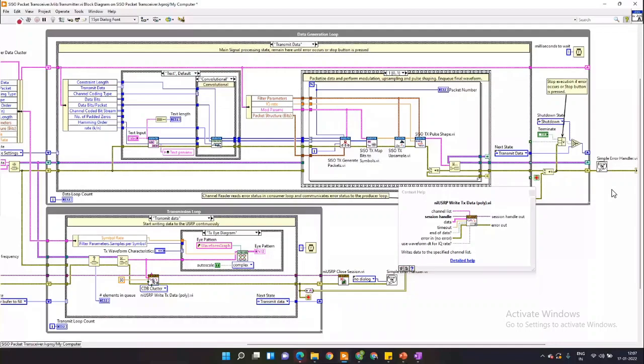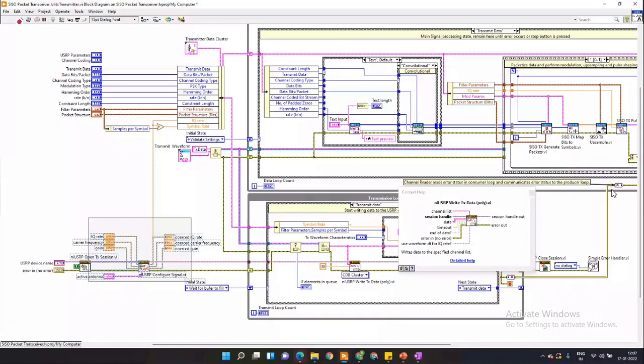And over here, you have a couple of configuration USRP APIs where you can specify the IQ rate, carrier frequency, gain, and then you get their coerced values. Like I said, carrier frequency you can set to even 10 gigahertz, but if the USRP is not capable, the driver will automatically detect that, and then it will say, I am only capable of putting it to this value, so I'll keep it to this value.